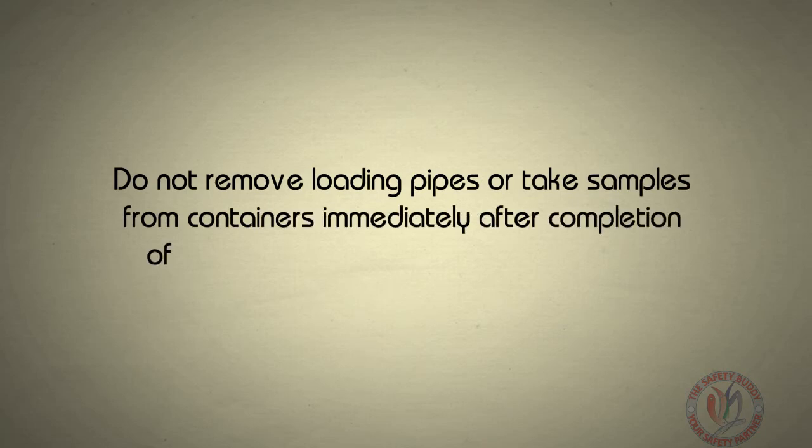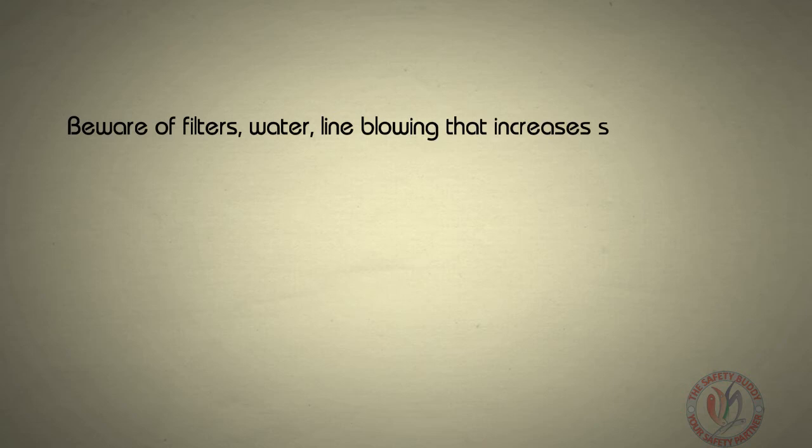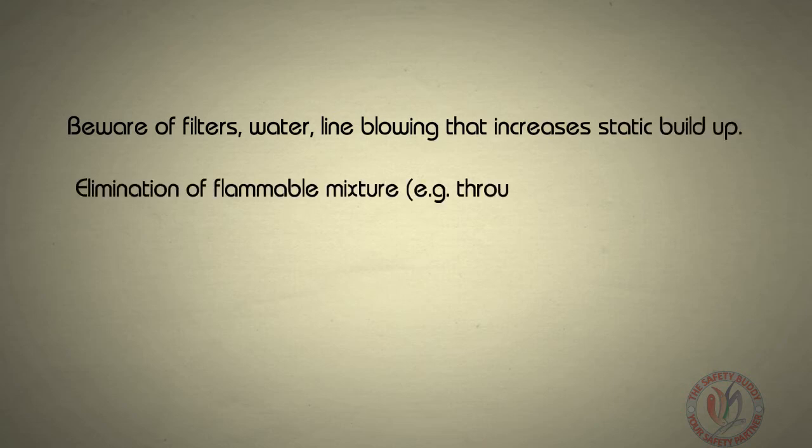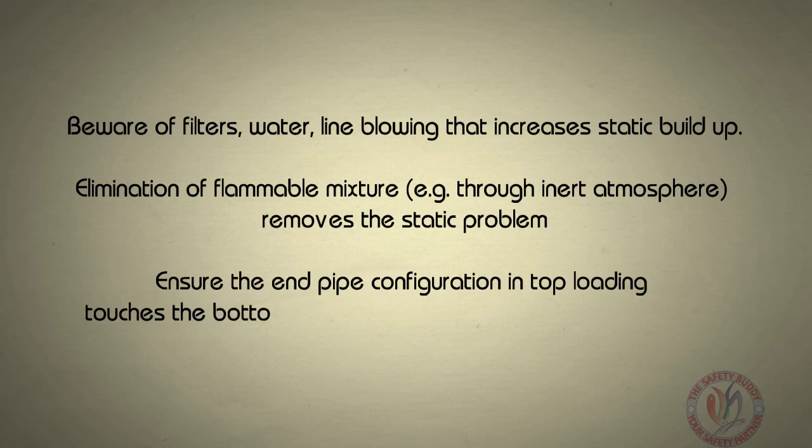Wait the required relaxation time. Beware of filters, water, line blowing that increases static buildup. Elimination of flammable mixture, e.g. through inert atmosphere, removes the static problem. Ensure the end pipe configuration in top loading touches the bottom of the compartment to avoid splash filling.